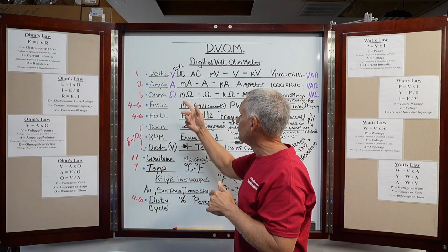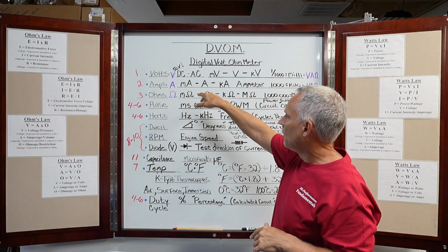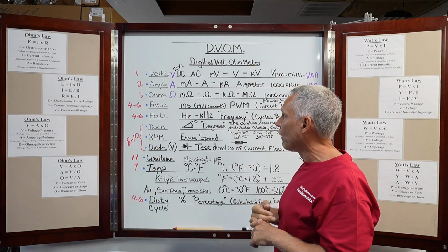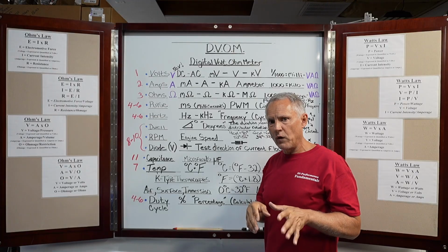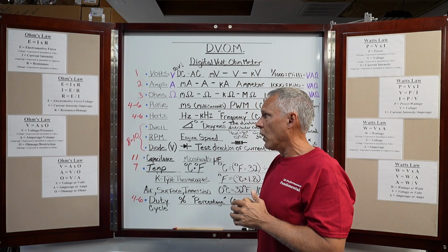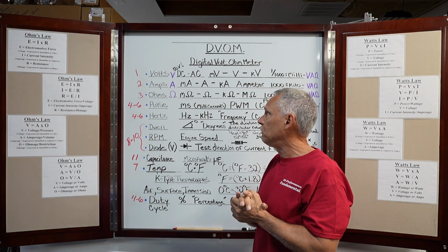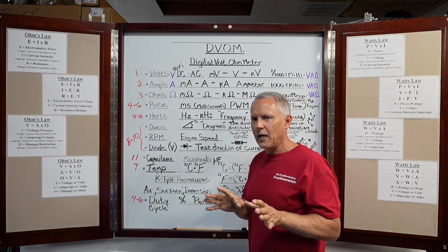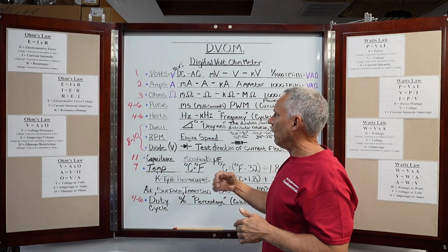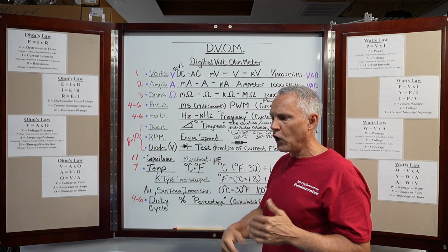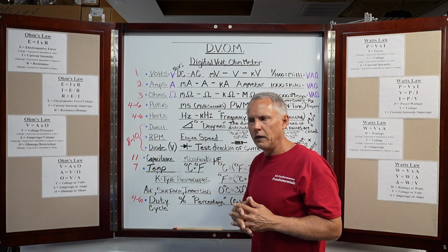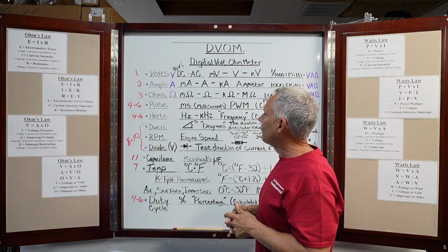So basically volts, you're going to need to select on your digital volt ohm meter whether you're measuring DC, direct current, or alternating current. The majority of the time, you're going to be measuring direct current. There are times in automotive applications that you will measure alternating current. It's not all that often, but you will at times. And usually if you're following a diagnostic path, it'll tell you to select AC or alternating current on the scale on your meter. Not only AC voltage, but also what scale. It'll actually tell you that in the diagnostic information or diagnostic flow chart. So you kind of will know.